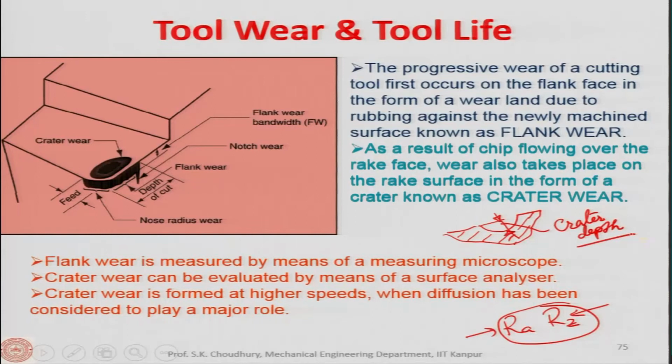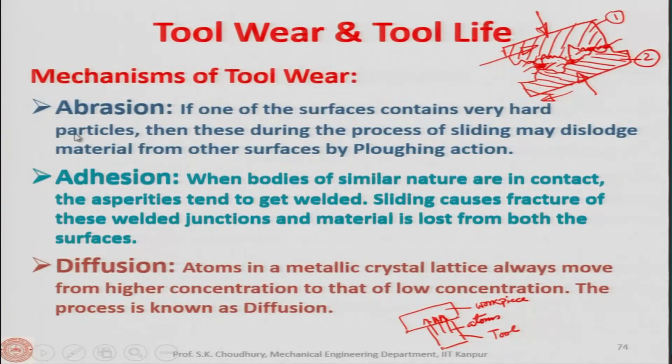Okay. This can be identified by the surface analyzer. Crater wear is formed at higher speeds when diffusion has been considered to play a major role. I already told you when we were discussing diffusion that atoms move from the higher concentration to the lower concentration.